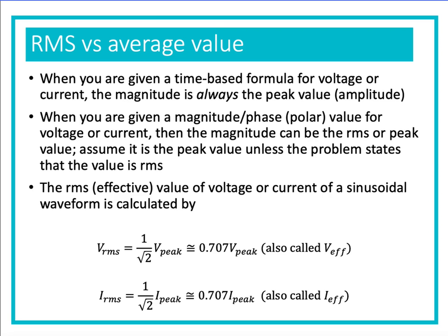We basically use an approximation formula to find the RMS value, and we approximate that by taking 0.707 times the peak value, and we will use that if we have a sinusoidal waveform, which we pretty much always will in here.